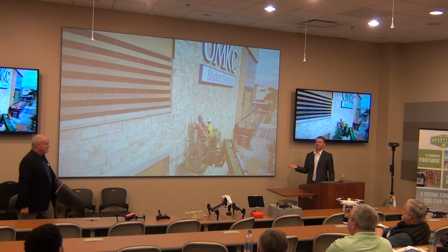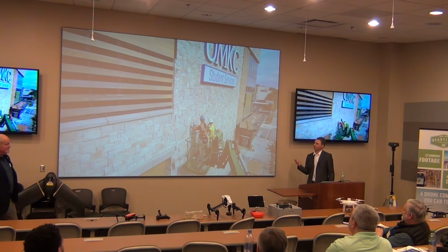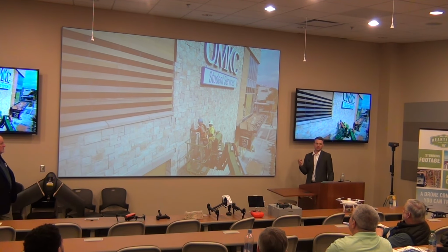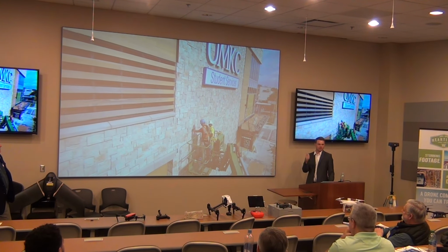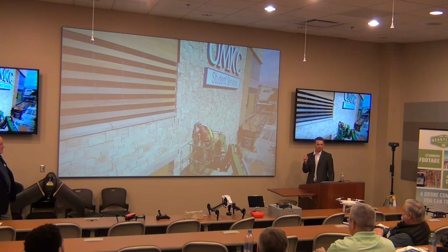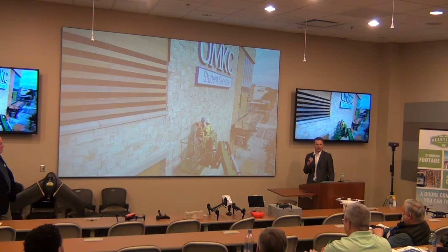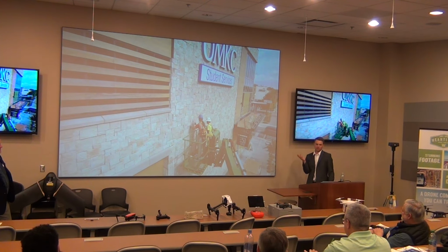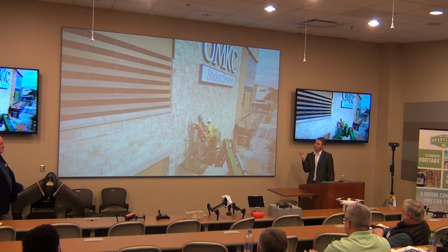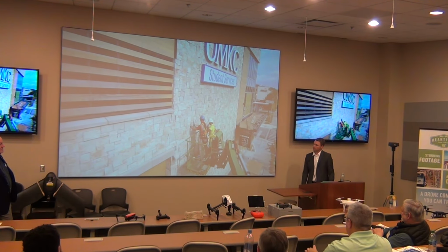So in this case, it saved the building owner about $50,000 to $60,000 because we were able to cut through all of the time spent doing this tap test for the engineer. We were able to cut through all that time by using the drone to capture the data, right? And this is just us truthing it. If the engineer was to do a tap test on 20,000 stones.